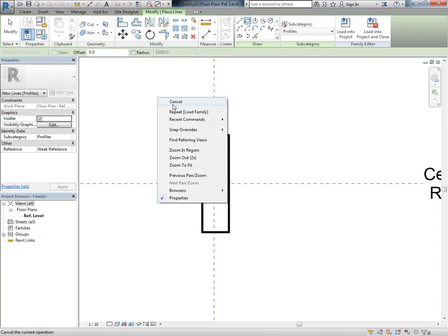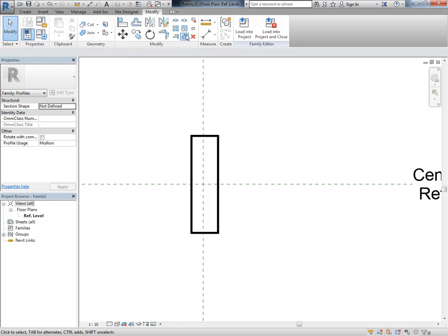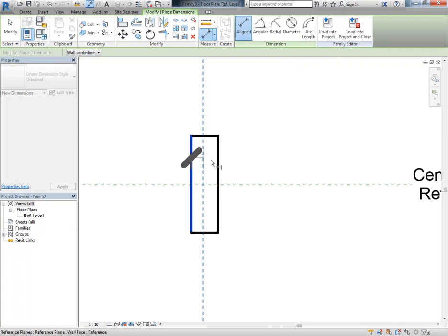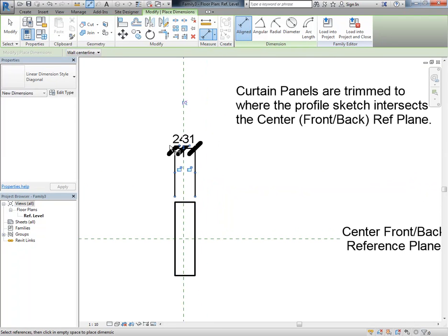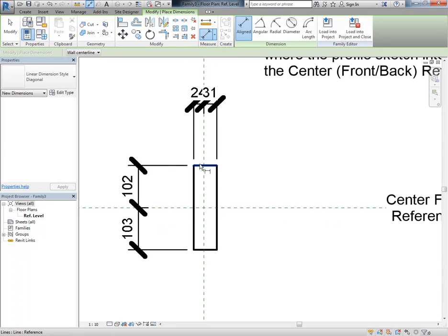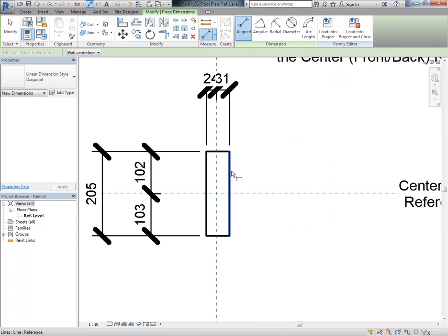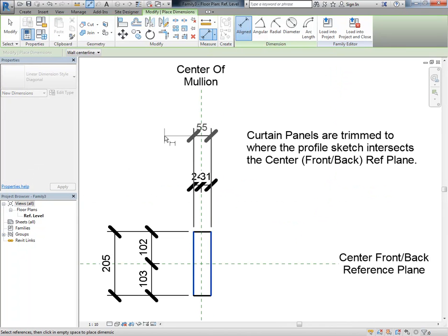And then, so hopefully getting used to drawing this way in Revit, just drawing things roughly the shape you need, then coming back and using things like dimensions to make it the right size. So I've drawn dimensions for the center line, now I'm drawing dimensions for the outer sides, or the outer edges.